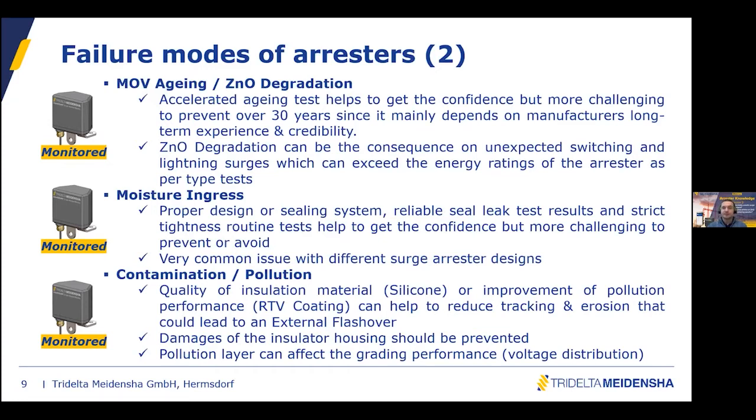You know that some surge arresters are equipped with a grading ring, and this grading ring helps for the voltage distribution along the MOV column. Sometimes it's not needed, sometimes it's needed, depending on the voltage level and the height of the arrestor. And for porcelain surge arresters, actually the thermal performance is affected by this pollution layer. So it's even more important for porcelain arresters to have reliable information about that.